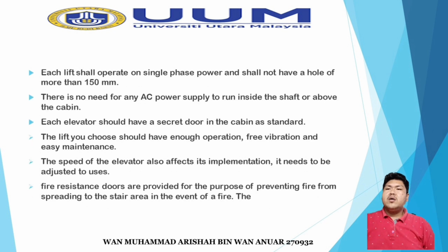Each lift shall operate on single phase power and shall not have a hole of more than 150 millimeters. Each elevator should have a security door in the cabin as standard. The lift you choose should have quiet operation, free of vibration, and easy maintenance. The speed of the elevator also affects the implementation. It needs to be adjusted to the users.